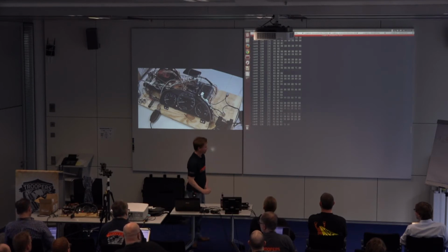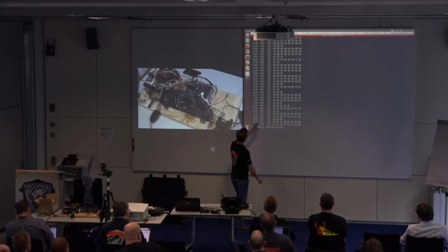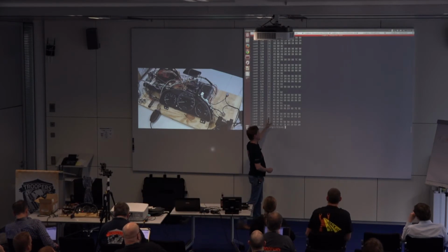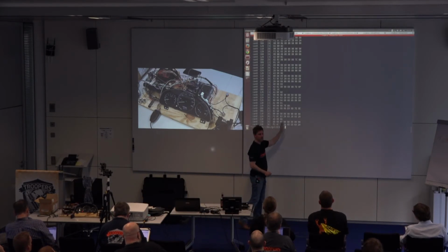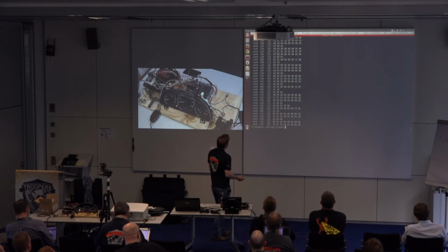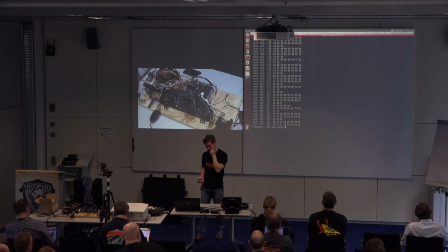Anyway, I'm going to stop it because it's too much scrolling. What you're seeing here is that arbitration ID I was talking about. And then you have your size, 3 bytes, 8 bytes. A lot of times with most vehicles, you actually see this always be 8, and they're just padded out, either with zeros or Fs or sometimes As. And so this is the CAN. There's really not much to it, it's just 8 bytes. Reverse engineering, it's not too hard.